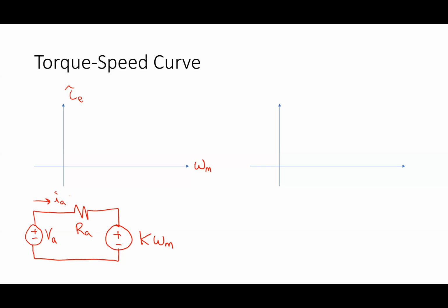What would happen if I increase the voltage? It'll spin faster. So take it to 3 volts. It's spinning faster. Now, if I grab the shaft and make it stop, what do you think the current's going to do? It hits 0.8 again. The reason is that's the maximum current this power supply is going to give me.